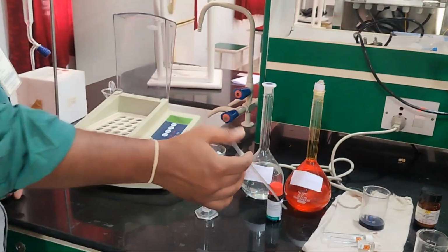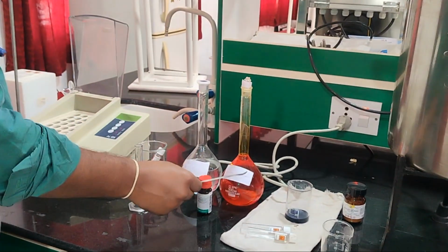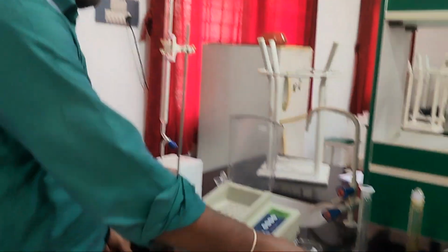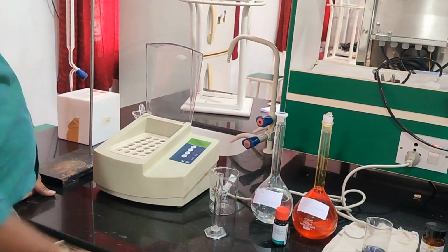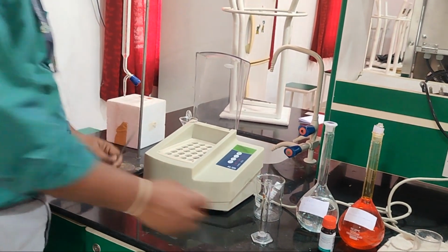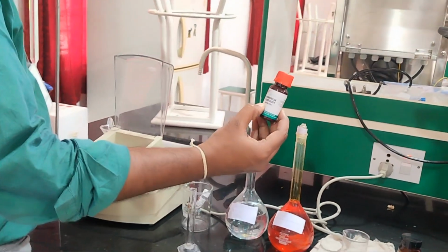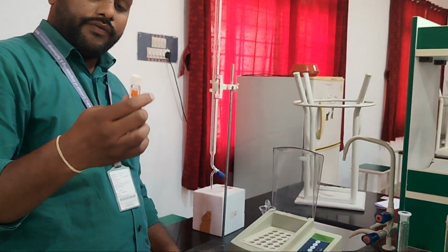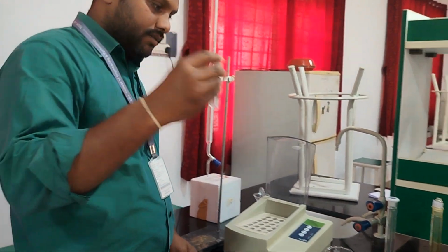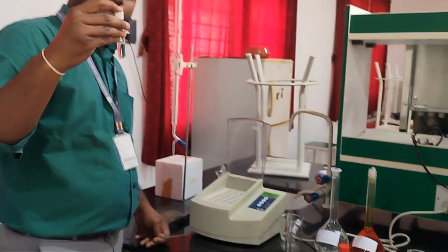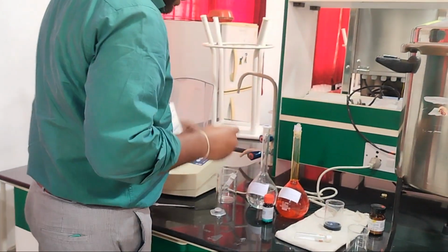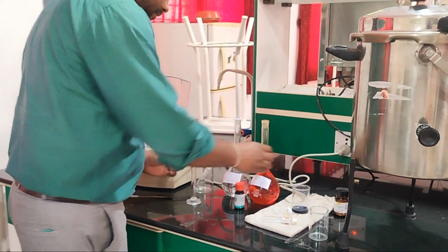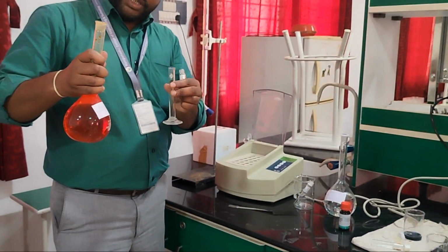Next, I have sulfuric acid and potassium dichromate with us. For the burette solution, I have already filled the burette with FAS, ferrous ammonium sulfate, of 0.025 N normality, and we have ferroin as an indicator. First you add the blank sample of 3 ml. The blank sample may be distilled water. Next I have the wastewater sample of 3 ml. Here I am adding 1.5 ml of potassium dichromate,